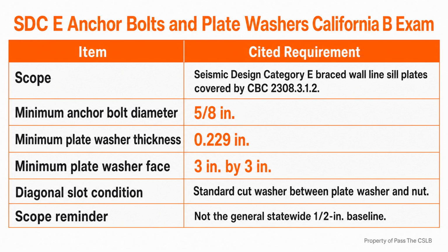The proper sequence is to stop work on the affected assembly, document the availability problem, and request formal approval from the architect or engineer of record through the required project change process. Where a construction change document is required, that document must be handled before the alternate becomes accepted work, along with any required building department acceptance. I keep the original specified installation in place unless and until the change is approved.